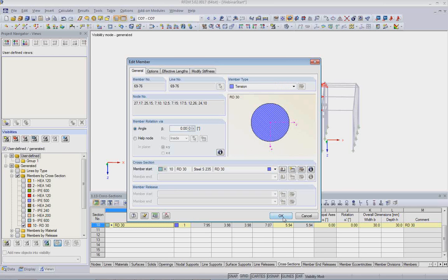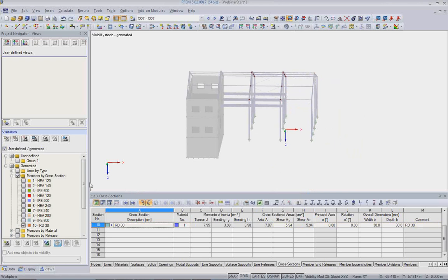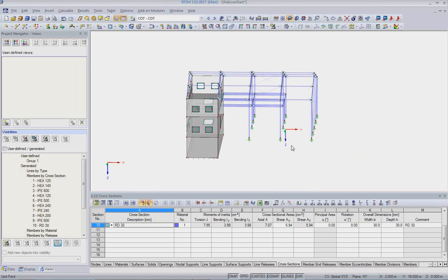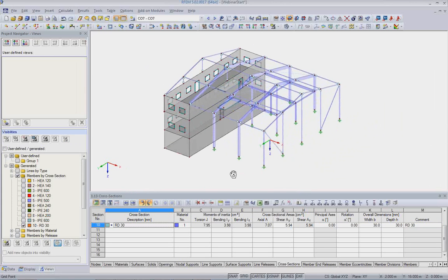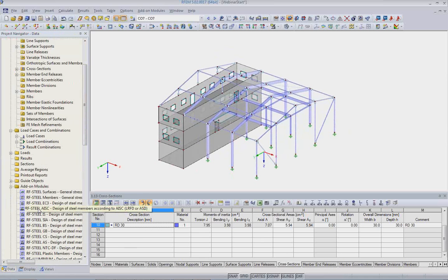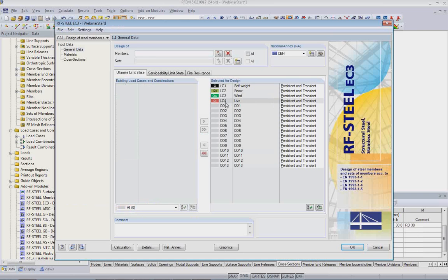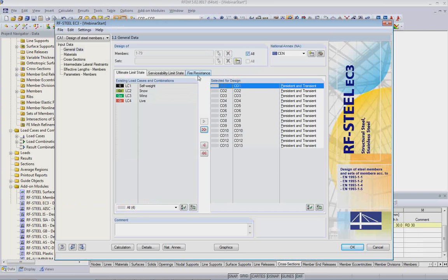So it's up to you whether you have to pack everything into Revit, or you may find everything there that you need or not. But anyway, some changes might be necessary, and one of them is the tension only setting that I do here. And now I go into our Eurocode 3 design module. Maybe I take care of the Eurocode design of the beams quickly. For now, I do just a brief conceptual design.